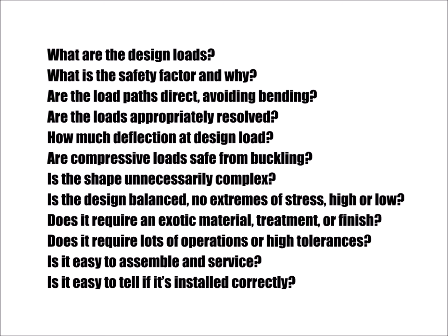In summary, consider the loads and how they flow through the part. Remember that a strong enough part can still be unsuitable if it deflects too much. Strive for a simple shape that experiences fairly even stress, avoiding concentrated weak zones and thick areas that add little to the structure. Finally, you want to be able to make and install the part with the least fuss possible.